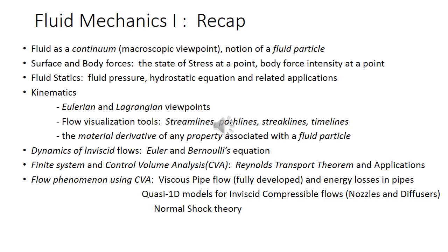Then to move further, we did some inviscid flow dynamics with the help of Euler and Bernoulli's equations. We later moved to finite system and control volume analysis in that course, and in control volume analysis we learnt an important principle by the name of Reynolds transport theorem. There were a lot of application-oriented examples where Reynolds transport theorem and physical principles were combined to obtain control volume equations of mass conservation, then momentum equations and so on, and you can compute some quantities of engineering interest, like gross quantities such as total forces as the fluid moves through a certain finite volume or region in space.